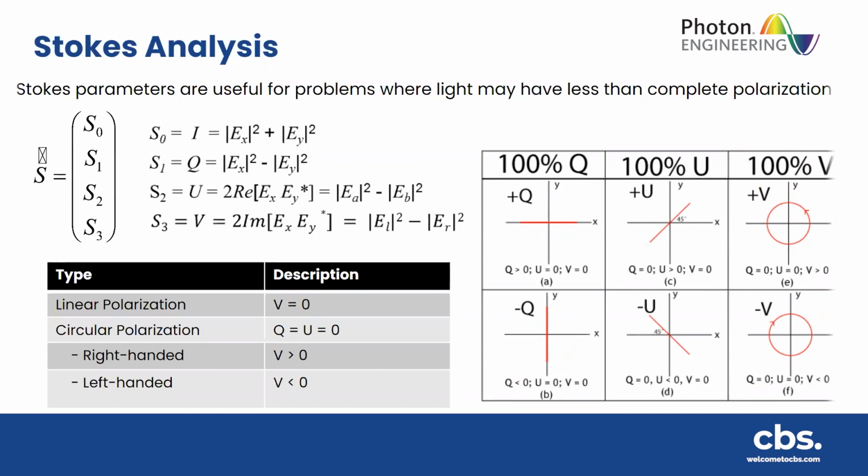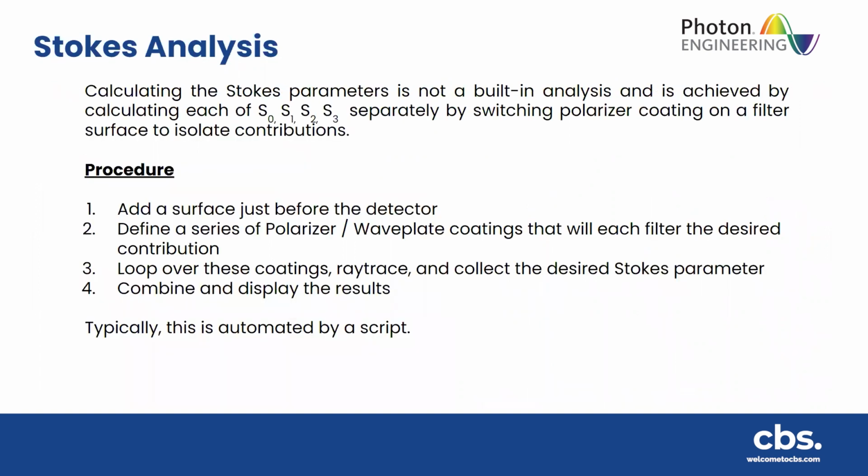Now, unfortunately, Fred doesn't have this option as a built-in analysis. So this is something that you typically do using a script, which Fred has a built-in version of BASIC that you can write these types of analyses yourself. The issue is we have to do multiple calculations on the same model, so if this is a huge calculation that takes an hour to ray trace, it's less of an attractive option.